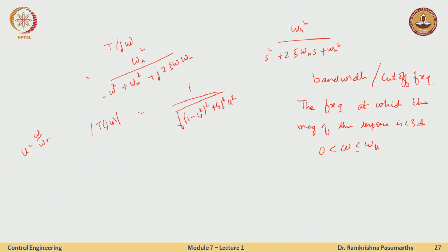Okay. So, how do we find this? We just take the transfer function and evaluate it to 1 over square root 2 in the absolute scale, or in the log scale, 20 log of T of j omega should be minus 3. Okay. Then I will just skip the computations because it is very manual, right.